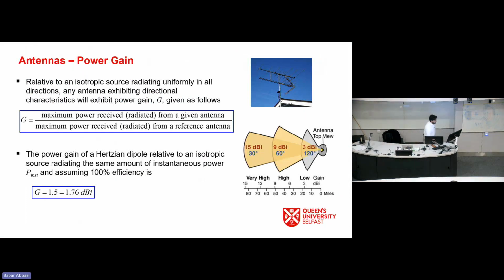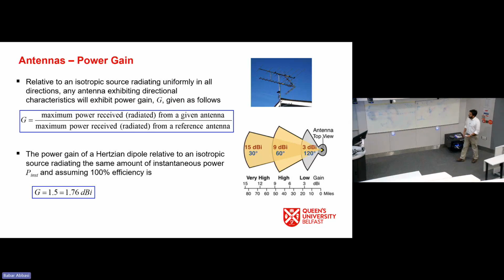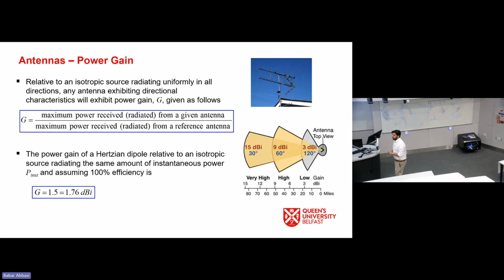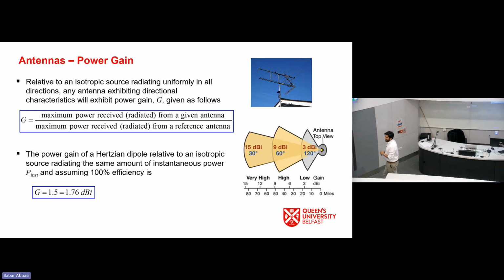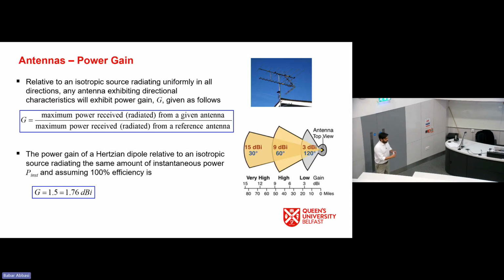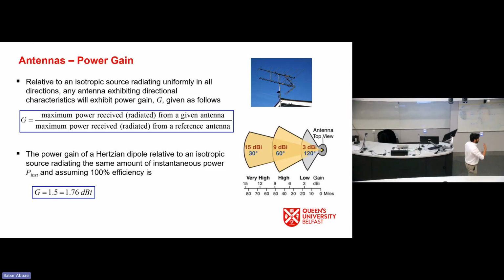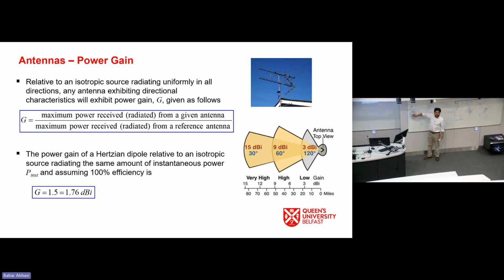Antenna power gain. Here's the concept. If I have an ideal antenna, it means it is radiating in all directions, but generating an ideal antenna is impossible. Directivity is very useful for defining how much an antenna is radiating, but practically it does not serve all the purposes. So here's a simple thing. Imagine I have an alternating voltage source connected to an antenna. Do you think all the power that I throw into the antenna is going to radiate?